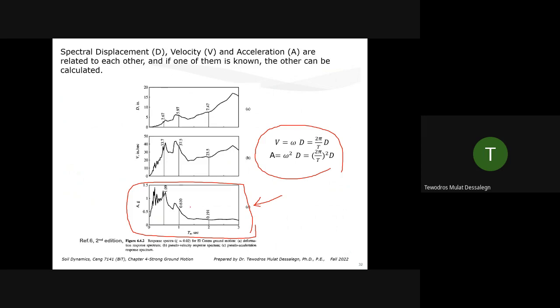Now, when you have a response spectrum, the big advantage is it gives you a quicker solution in the software. It's also advantageous for a static solution. If I know the fundamental period of my structure, let's say I have a period of 0.5, then the corresponding value is 1.09. So this is the acceleration you'd be using for design. There are other factors to include, some amplification, some conservatism.